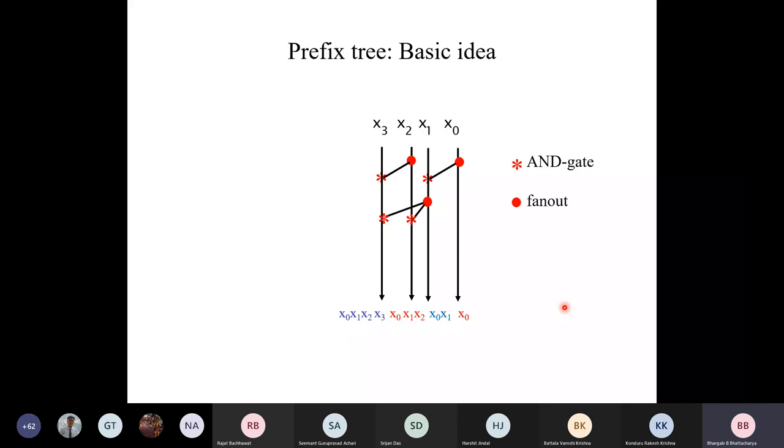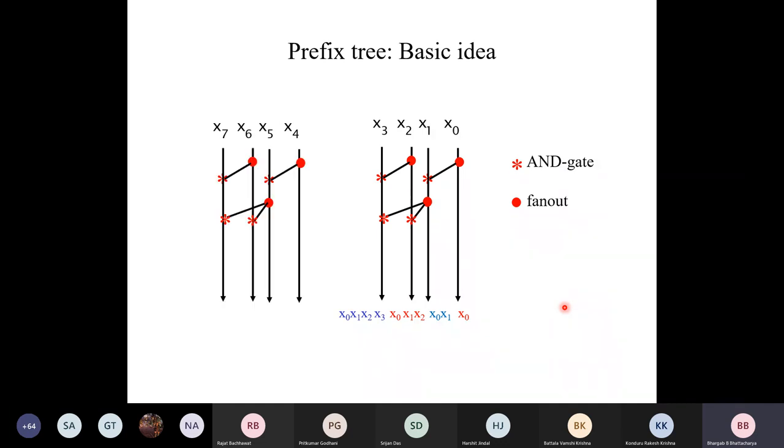See, you have used this kind of technique many times elsewhere, I guess. You have solved this half of the problem, and then you have to expand this for the other half. Now my input is x0, x1 up to x7. So there are other 4 literals, x4 to x7. Sir, we repeat this same thing again and make a connection from x3 to x4 and x5. Exactly. Brilliant. That's what I was waiting to hear from you. Yes, correct. So you repeat this thing.